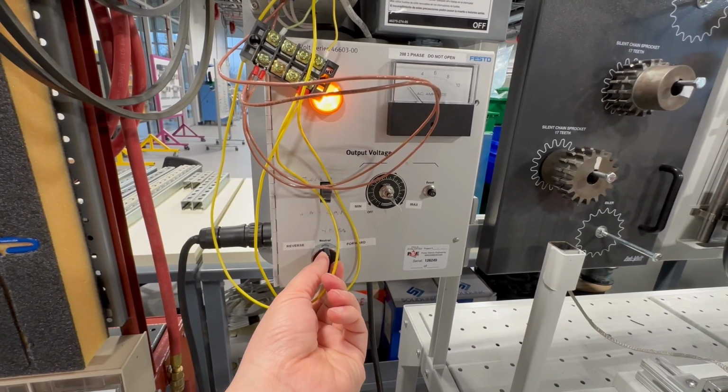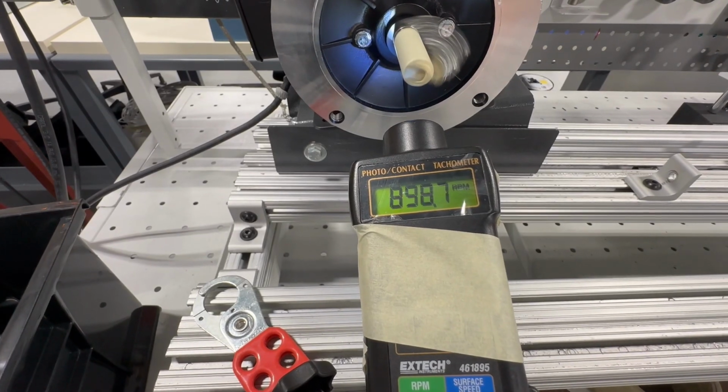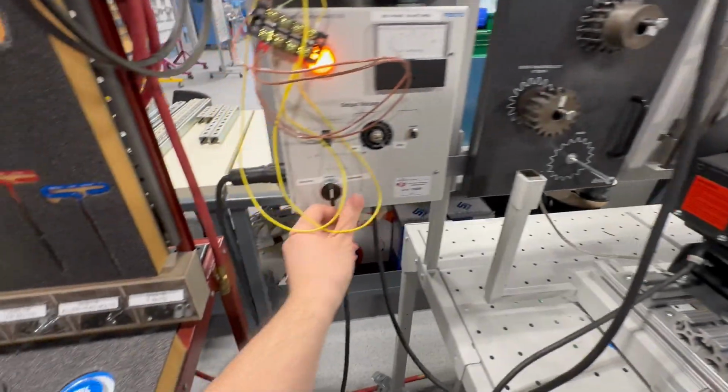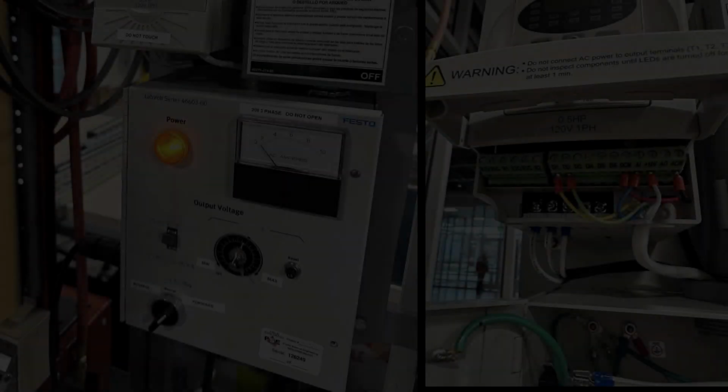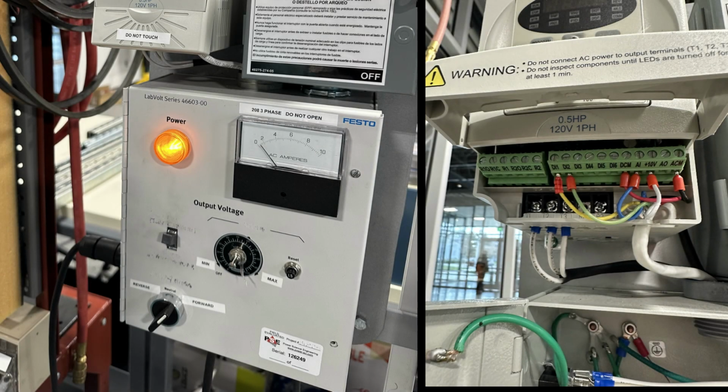Our goal for this lab is setting up the VFD to control the motor to run forward at around 900 RPM and reverse at around 425 RPM. The VFD we are using right now gets direction selection from the external control, using DI1 and DI2 digital inputs. When DI1 is set, the motor will run clockwise. When DI2 is set, the motor will run counterclockwise.